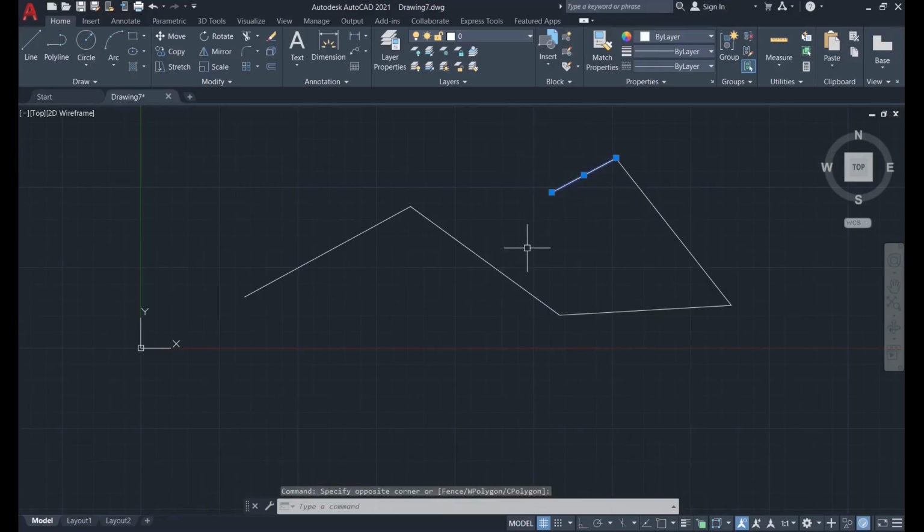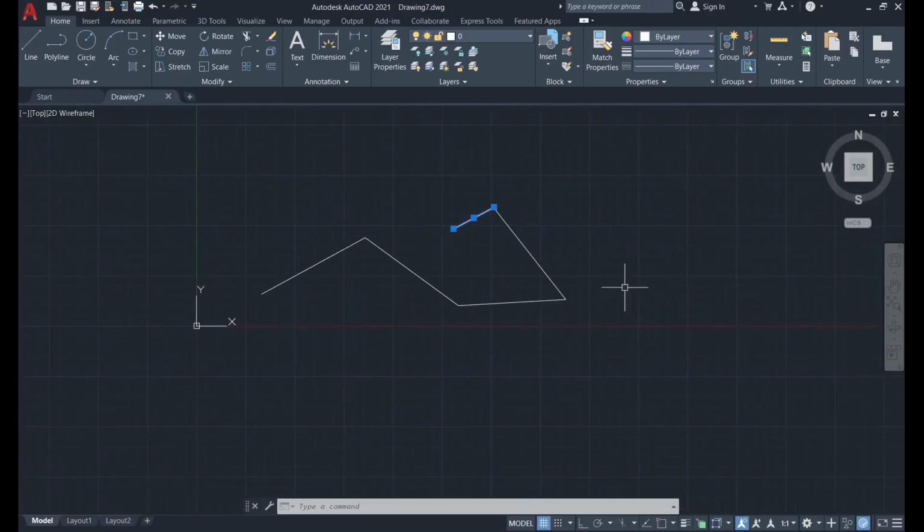Make sure to practice this selection because it will be very helpful when you have a lot of objects on your screen, when the drawings get busy with many lines, objects and so on. You will want to select some lines without touching others, so you want to use the green or the blue selection then.